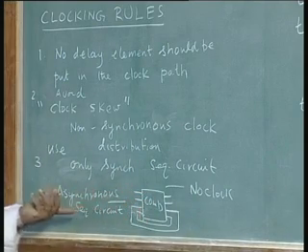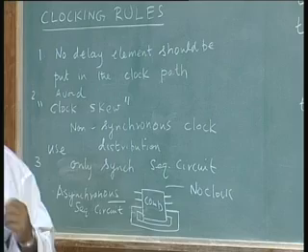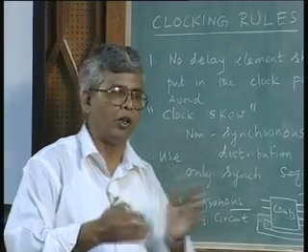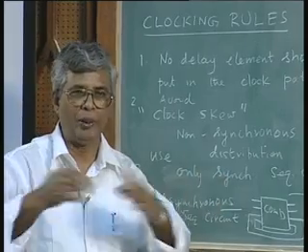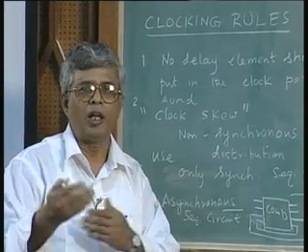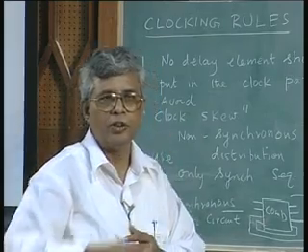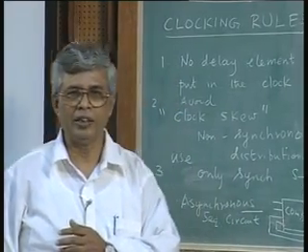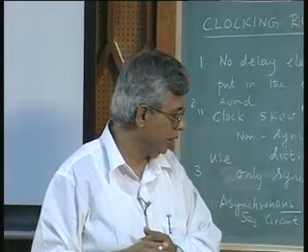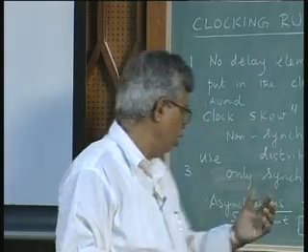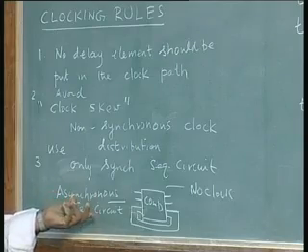This is done in extreme cases where your speed of operation is so important, or because you have no clocking strategy between two circuits you are designing which are totally independent of each other, where there is no common clocking scheme. Your clocking scheme is different from the circuit to which you are going to interface. There may be several reasons why you may have to go for an asynchronous sequential circuit.